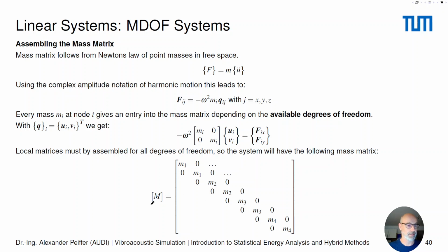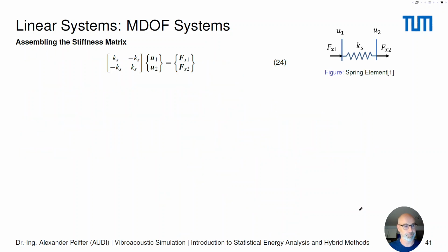So again, this mass matrix is quite simple for this lumped element case, and it's always a diagonal. If we have a global system from an FE system, it might not be a diagonal matrix, but it will always be a banded matrix. So for the off-diagonal, there will not be many non-zeros except near the diagonal.